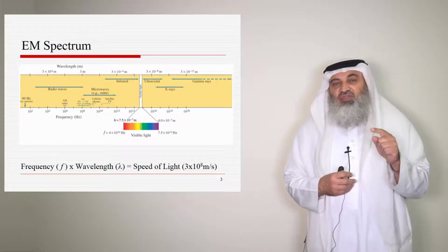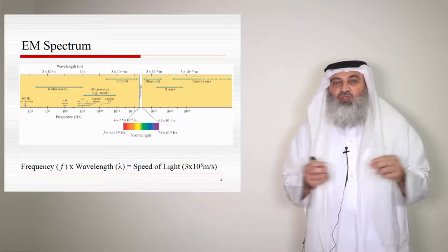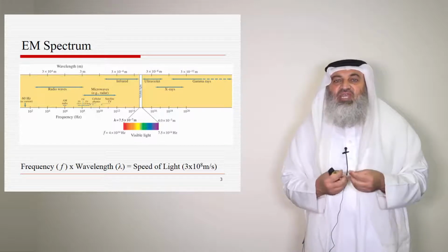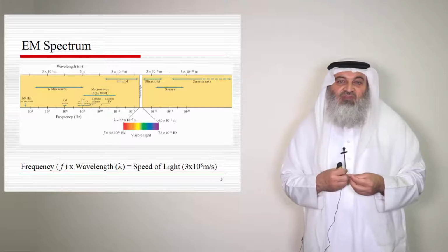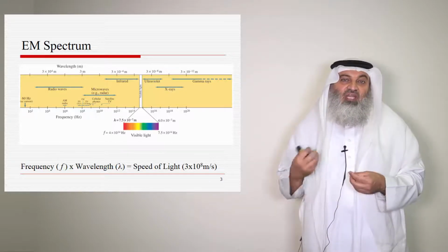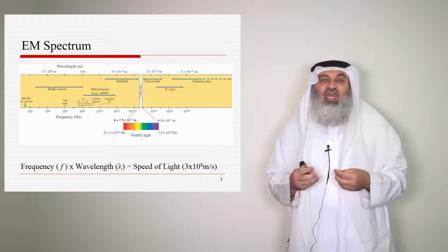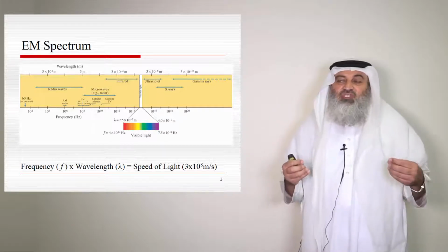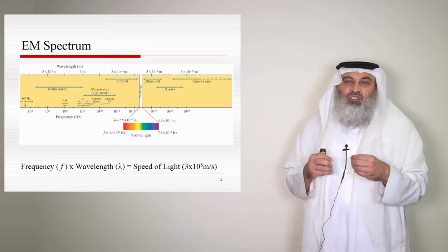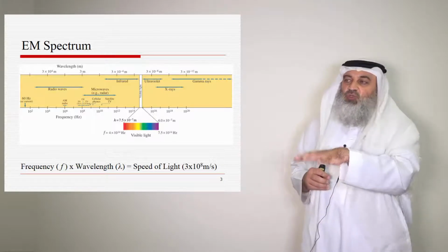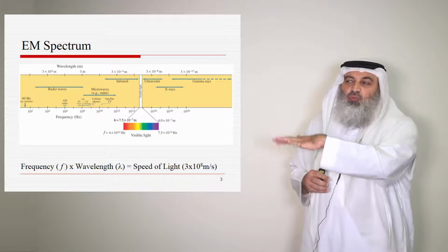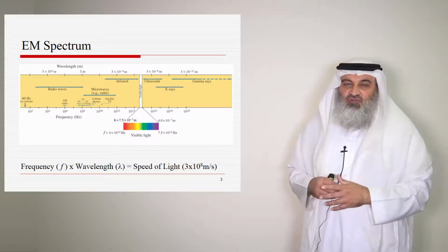If you recall that, we said that the size of the antenna you need for broadcasting is related to the frequency of the signal or to the wavelength of the signal. And if the signal has a low frequency or a large wavelength, then the antenna size would be huge. This is why it's not feasible to design antennas for broadcasting at very low frequencies. So we don't see any broadcasting in the low part of the spectrum.